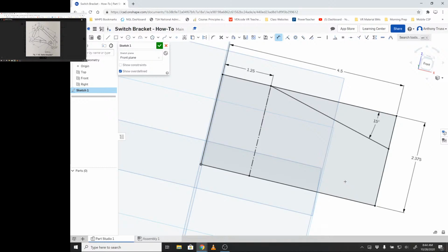And so we're going to press M as in Mary, or the last letter of the word trim, or you can click the scissor icon here. And then if you hover over various geometry, you'll see that it turns orange at intersection, right? If I hover my mouse over the orange line that you see here, the entire vertical line is not orange, just where the intersection takes place between the top and the bottom of that line segment. So if I click, that line literally goes away.